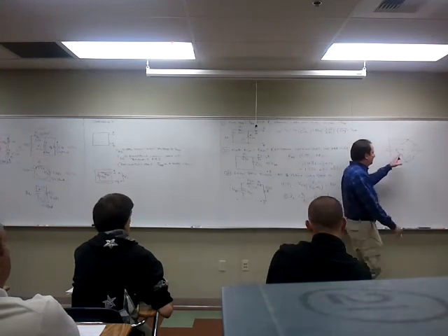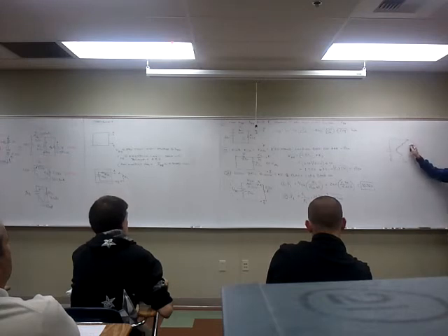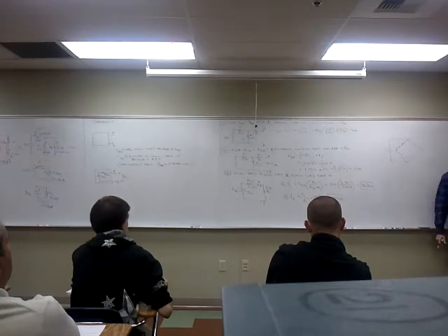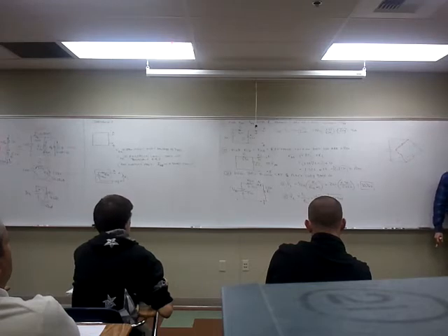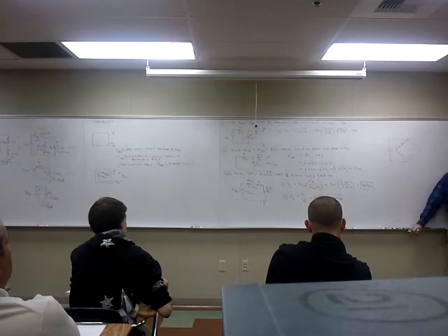If you remove that resistor, now, what kind of circuit do you have? 2 series. Exactly, 2 series. These 2 resistors are in series, those 2 resistors are in series. Add them all up. It is now solvable, isn't it? Because you have 2 series branches in parallel with each other. You can solve this circuit. So that when you had the resistor here, you could not solve it by normal series parallel techniques. You had to use some network theorem.